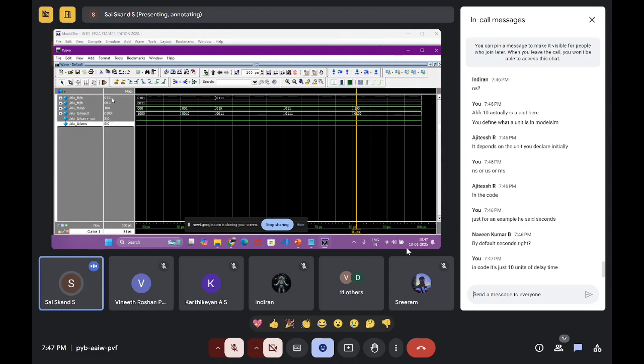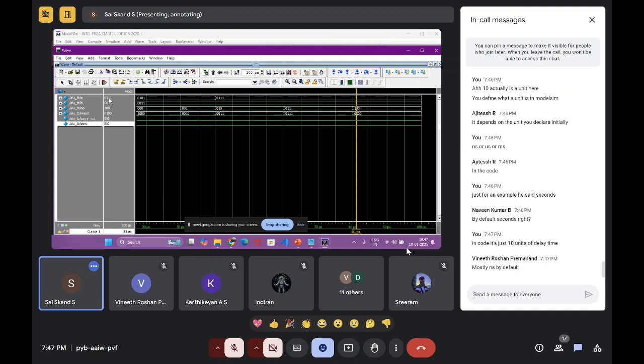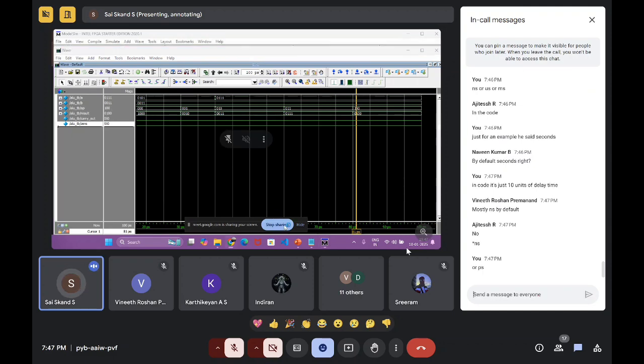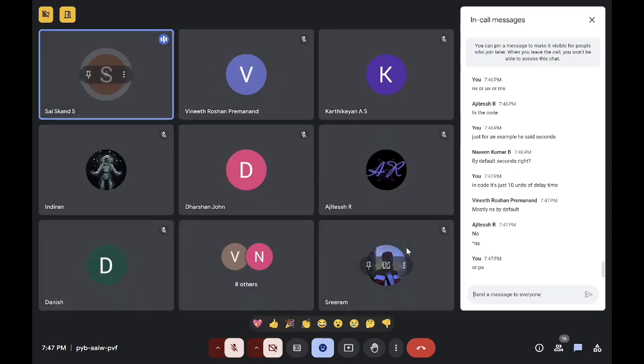So we're getting the results 1 1 0. 1 XOR 1 should be 0, and 1 XOR 0 is 1. I guess that's clear. So we're getting the result. This is our basic implementation part for an ALU. I guess you're clear with that. I guess you understood.